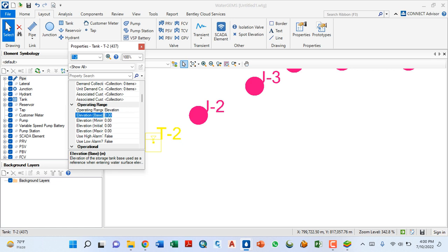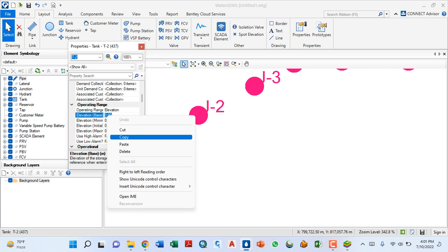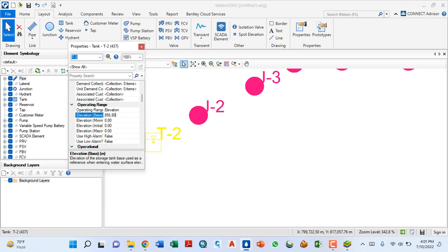If your tank is a ground tank, don't worry. Here is the ground, so let me add the foundation of the tank. The foundation can be 50 centimeters. So add 50 centimeters to this one. 0.3, 7.3. It became 7.3.